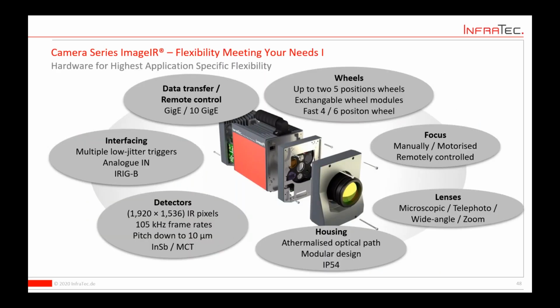This very camera series is really based on a flexible approach. The camera is based on different modules that can be combined for different detectors, spectral filters for different ranges, motorized focus options, and different kinds of interfacing: GigE, 10 GigE, but also advanced trigger interfaces, for instance with different analog inputs as well as digital inputs.